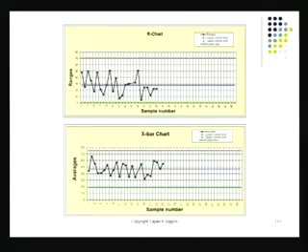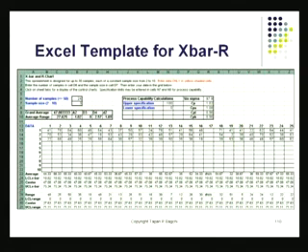So to me, it was just amazing that this man knew the value of producing data and using that as feedback right then and there. And that's the beauty of these control charts. If you use them right, they will tell you right away that the signal is there. So what charts are we looking at? The first chart is, of course, the X bar chart, the R chart. It's like the first chart you can construct very easily using Excel.